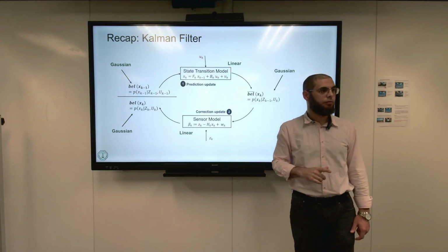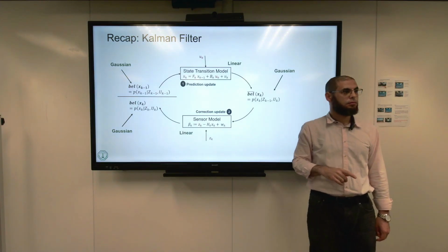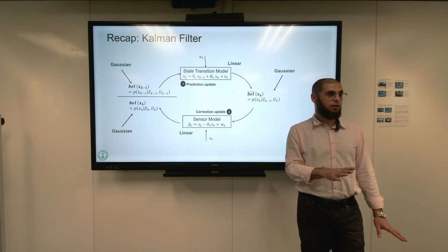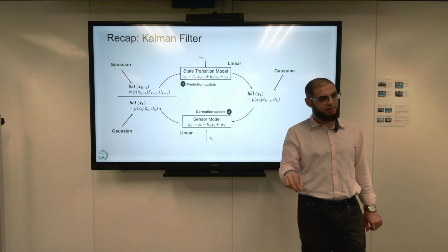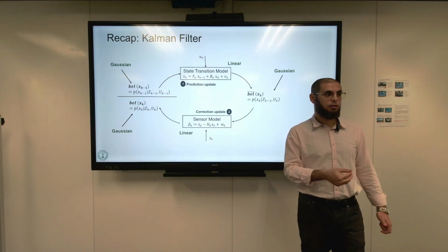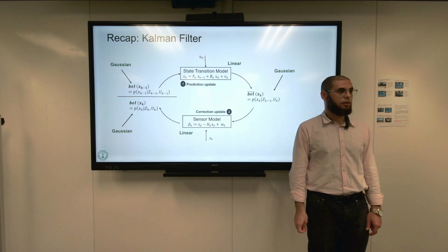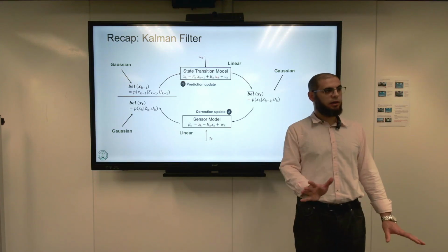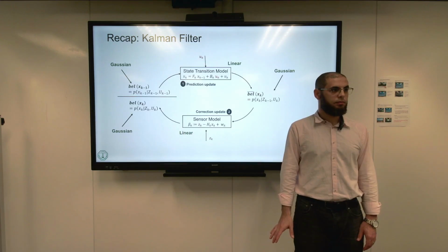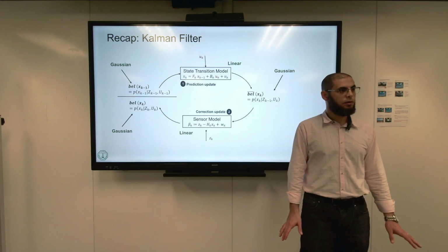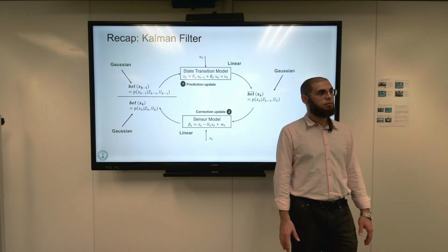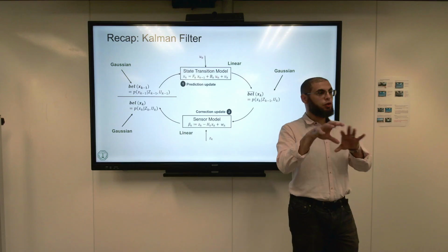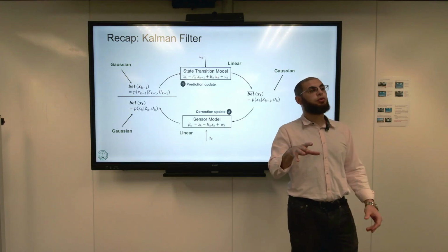This is Muhammad. Do the two sensors have to measure the same state, whatever they want to sense? That's an excellent question. Are you saying they should be exactly the same state, or should they be related to the state? Not the same state. For example, we have an accelerometer, which calculates the acceleration. That's right. And we have another sensor, like a camera, sensing the surroundings. From the raw image you can do some post-processing, and then you can transform it into some velocity of the robot.